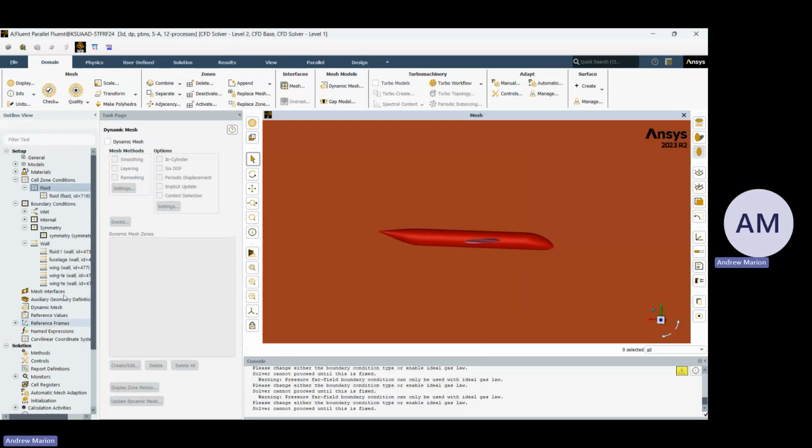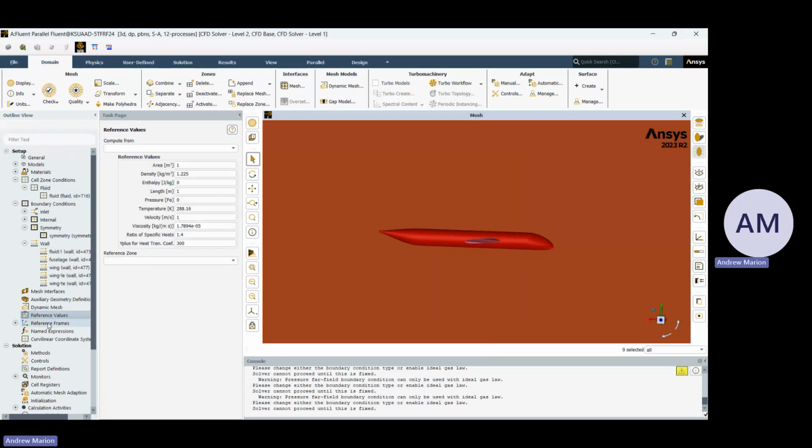You can just make up funny names for it, but if you want to be quicker with your simulations, I recommend keeping to a standard practice of far field, inlet, outlet, if you have those in your model. Naming a wing a wing, that way Ansys speeds up and knows what you want to do without you having to input those for it.